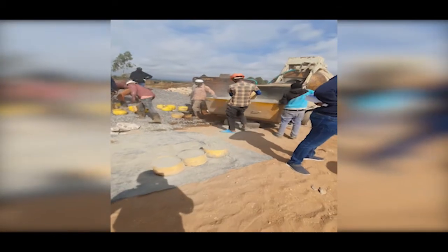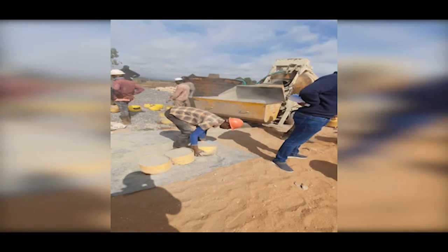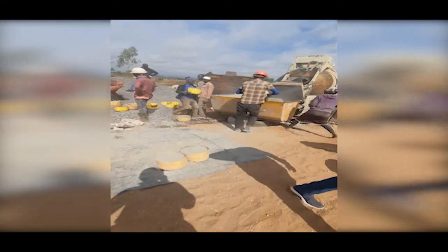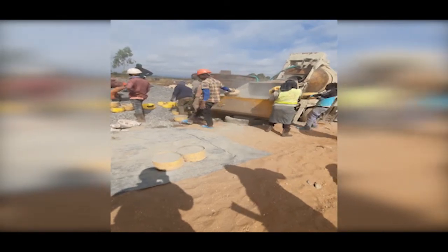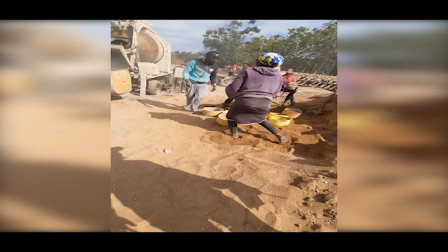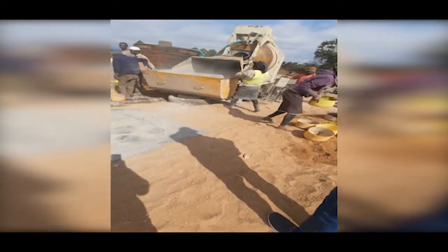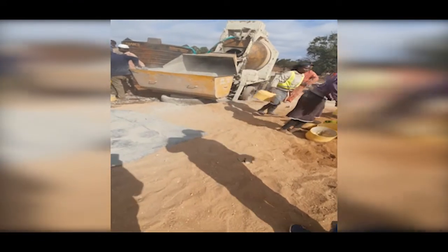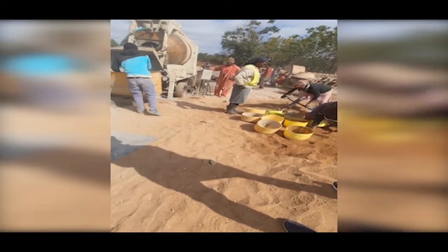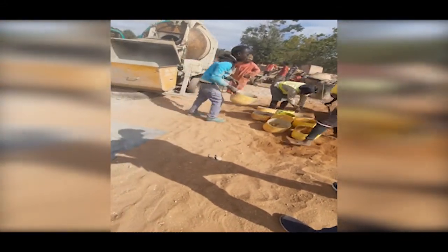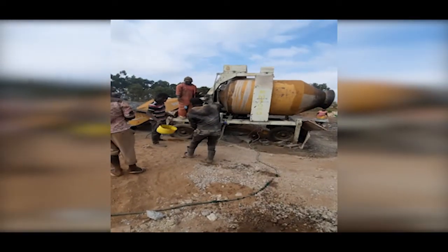these items are usually weighed using weighing scales that you'd find on the batching yard or batching plants. And you'll find that when you're batching by weight, your target strength, plus or minus, does not go so far away from what you'd expect. So you are more or less sure that you're going to get what your mix design indicates in terms of strength. So batching by weight is usually a good way to go.